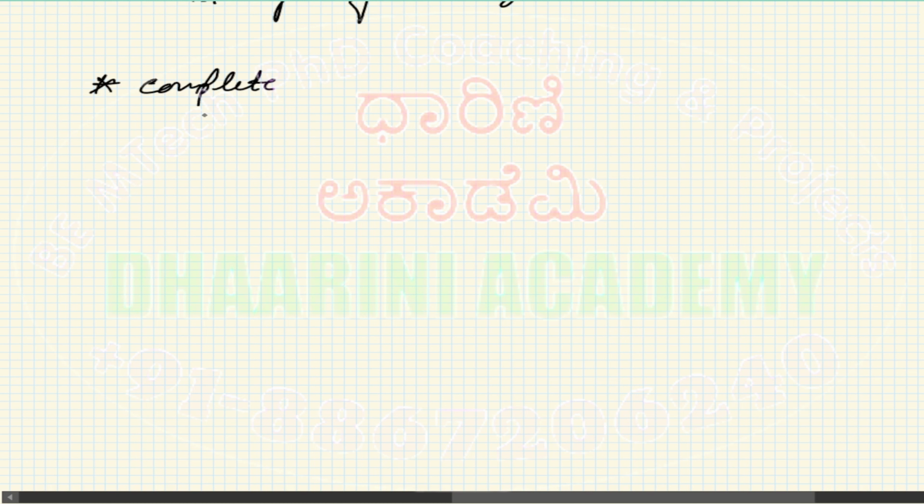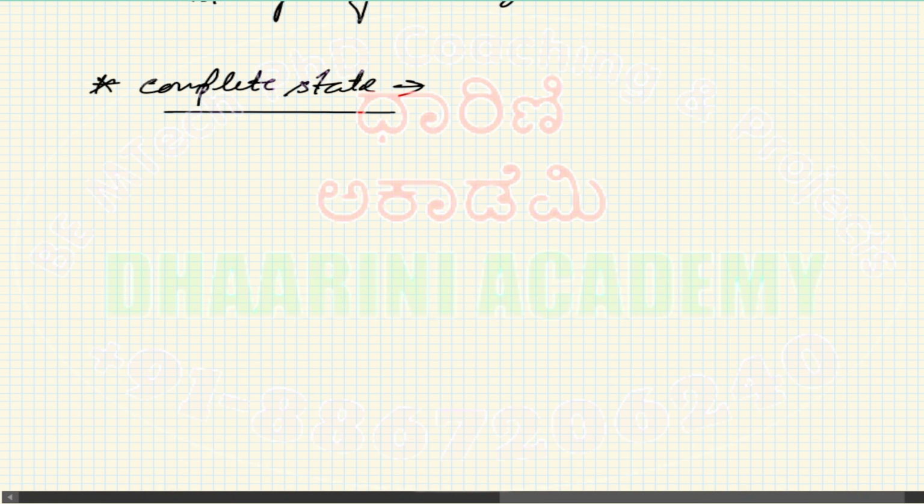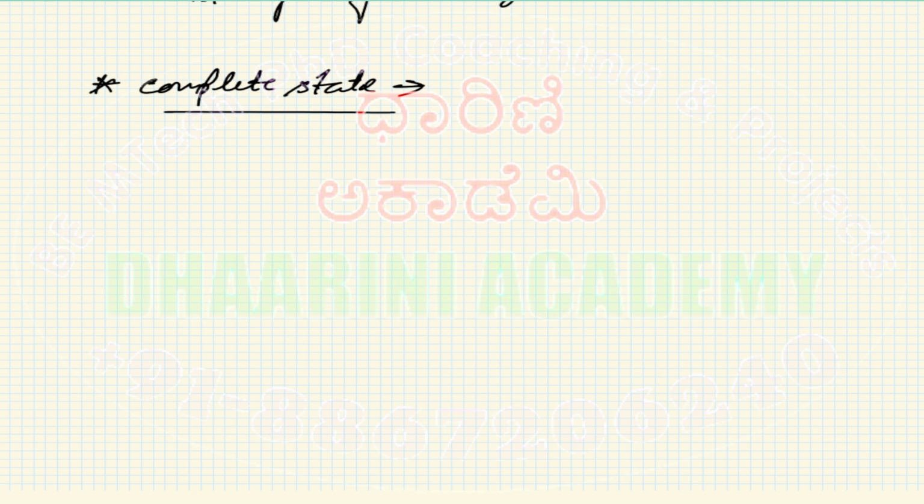I want to define a complete state of a system. So this is what is the actual state. The previous one was just a general statement. We can try to write the initial conditions of every element. I have maybe two inductors, three capacitors. Inductors are also going to have memory, right? Current in an inductor looks like a memory element. So inductors will have some initial currents I1, I2, I3. Across the capacitors you have some initial voltages like V1, V2.